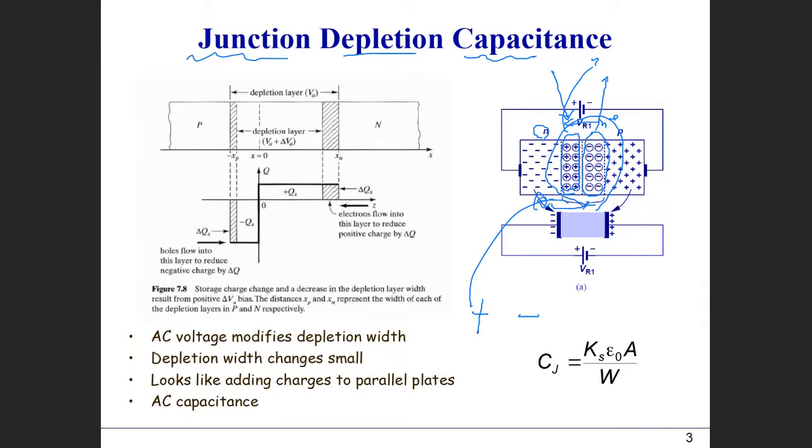This concept is very similar to the typical parallel plate capacitance. In a plate capacitor, we form the capacitor by using an insulator material between two electrodes. With this kind of structure, the charges cannot pass through the insulator. So when you have an applied bias, you have a physical separation of charge. The PN junction diode is, in some sense, very similar to a typical plate capacitor.